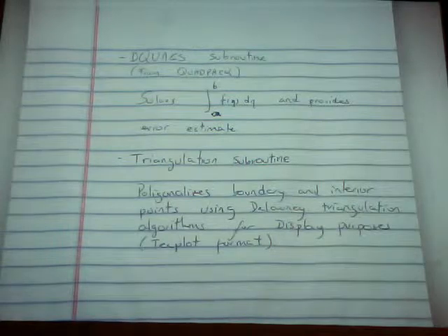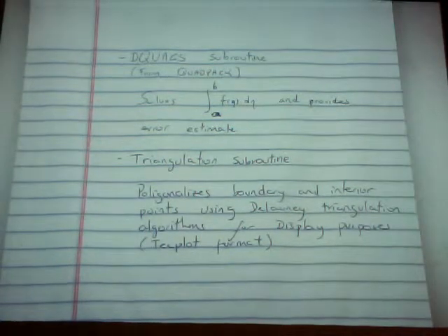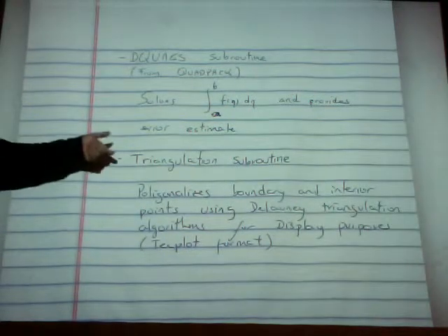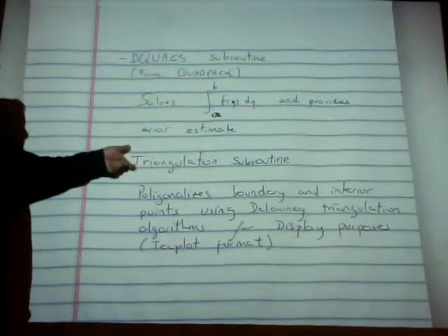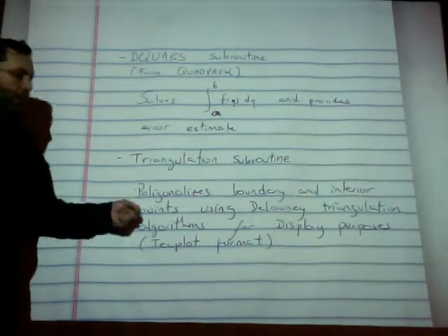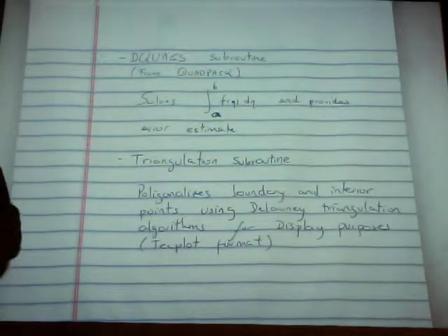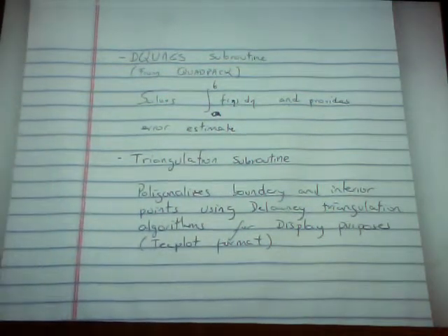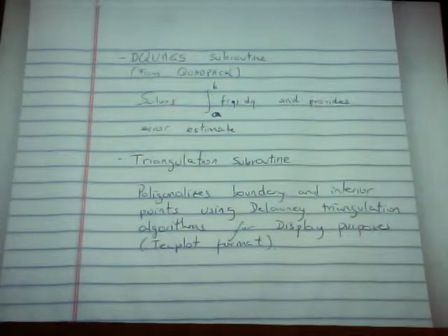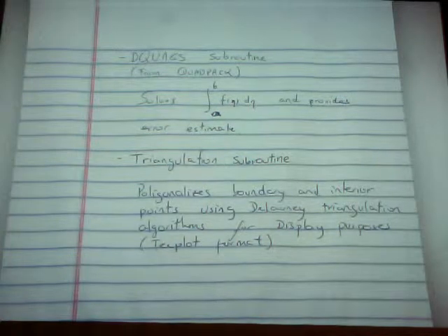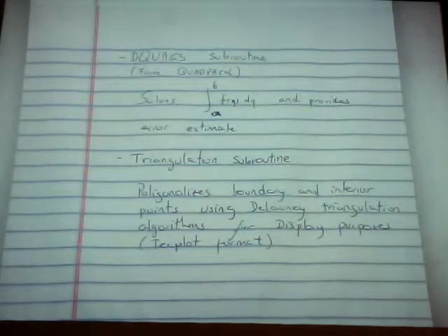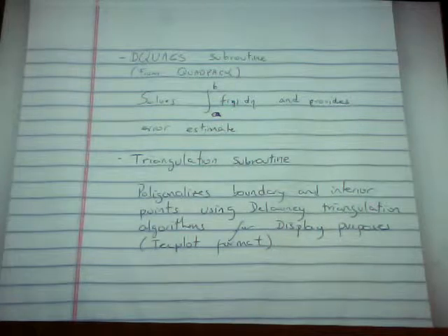It does have an internal triangulation routine, TecPlot does, but then you have to go through the process of doing that every time. So in order to avoid that, I've used a triangulation routine to create the triangulated data, that means connectivity between points to form triangles, and export that to TecPlot so that TecPlot automatically displays the data for you on any computer on campus. So you can produce contour plots and vector plots and so on. All right, so that's it.